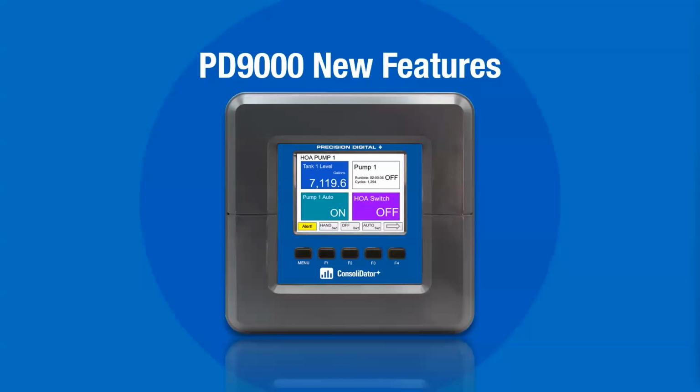You can have 4 to 20 milliamp outputs that are scaled across that total. You can have timers that, for example, reset the total for you at a specific time of day. All sorts of nice totalization features you can do. And so the answer to this is yes, you can absolutely do all those totalization features. You don't use the timer just to set up a simple total. You just have a total option for that. It's its own function.